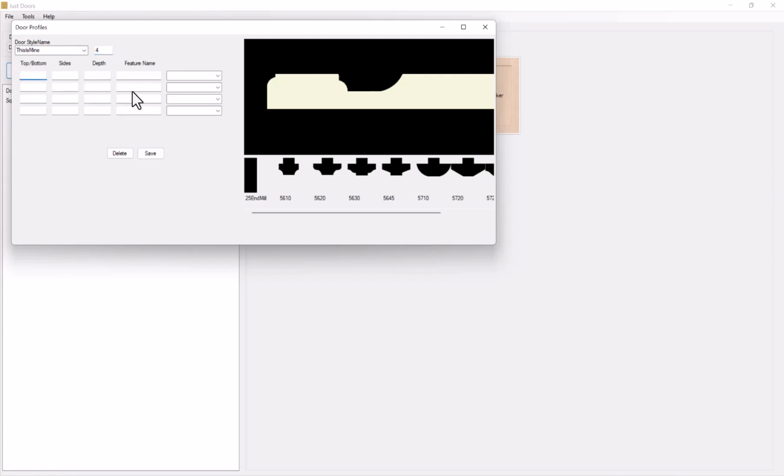And then we will enter in the values of the offsets. So we will have a -1/8 quarter of an inch for the outside edge. 0.3, and just give it a name. This is the name that we will be using to create the profile. And then we would select the cutter profile that we want here.